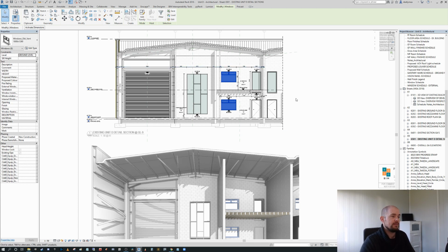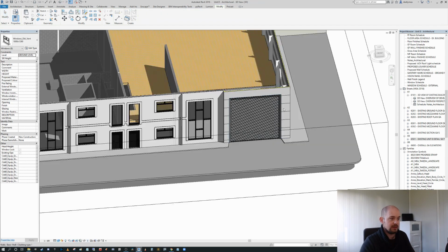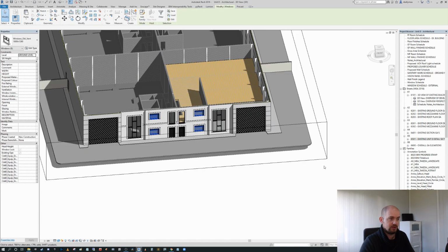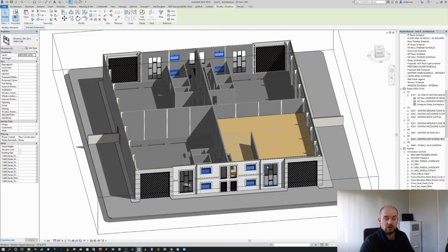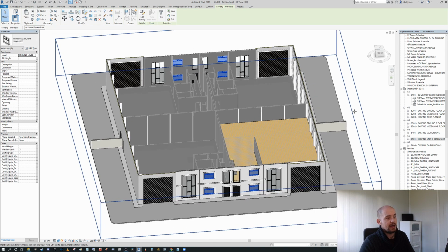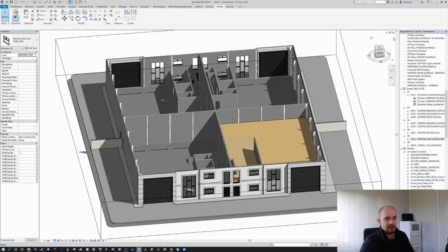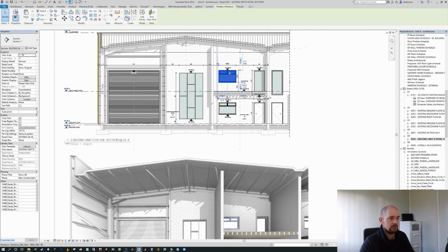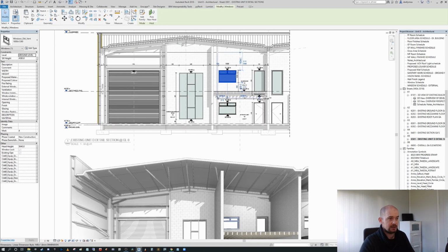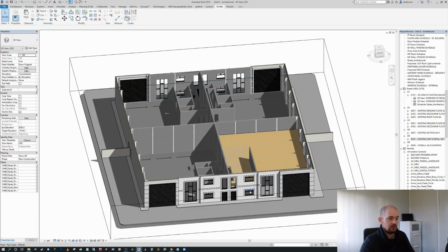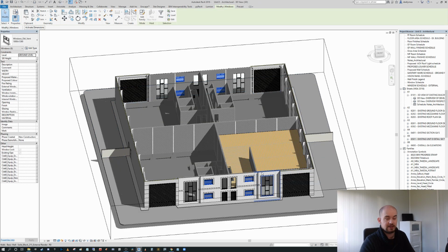All right, so going into 3D view, you will see that selection. So if I select previous, that selection is across all 8. Okay, and what's interesting about this is there's actually a shortcut key for this as well. So when we have the window that we want selected, and we want to select all instances in the entire project, if we just type in SA, it'll select all. But you'll notice again in the properties tab that we have 8 total selected. So when I go into the 3D view, I can select one of those, press SA, and it's going to select every instance of that in the entire project.